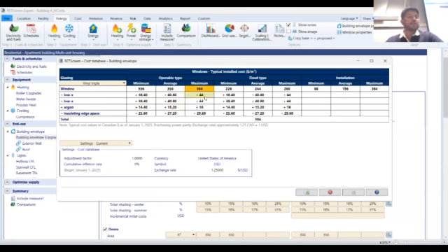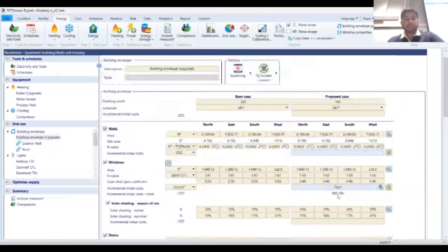I know it's a single low E, not double, so I'm only going to select one. I know it's argon filled. I know it has an insulating edge space. And for installation, I'm also going to select the maximum value again to be conservative. If your window was a fixed type, you could select the values from the fixed type columns. And finally, you paste the data, and your total value of replacing the windows is about $400,000.